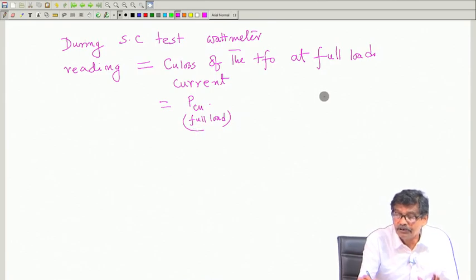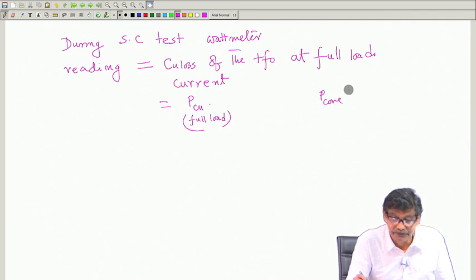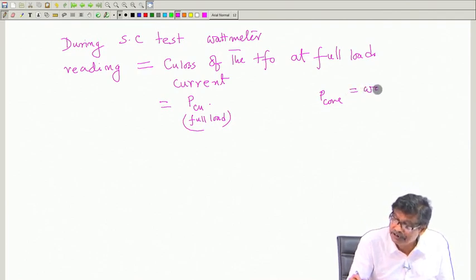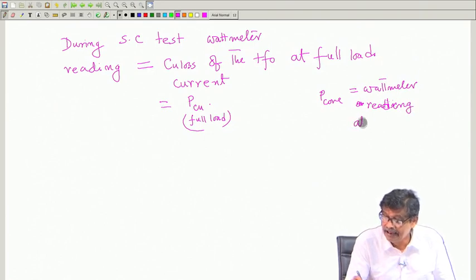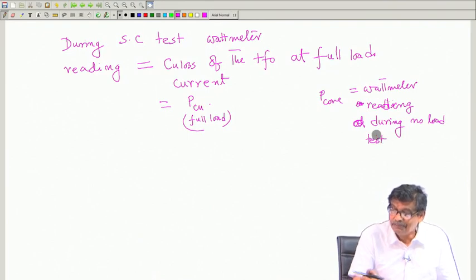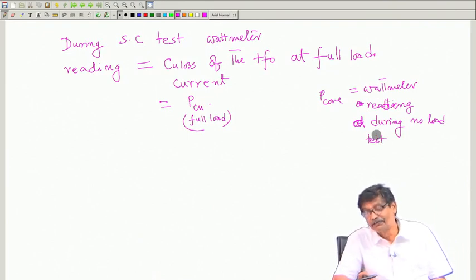And P core is equal to the wattmeter reading during no load test, because I have applied rated voltage, rated frequency.